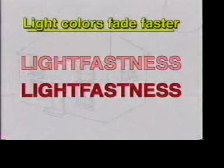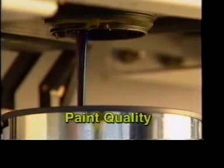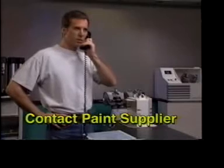This can be caused by differing levels of light fastness of pigments in a blend, or by certain combinations of organic and inorganic colorants. In pigments that are light sensitive, light colors fade faster than dark colors. For instance, a light pink will fade more than a deep red if the red pigment involved is light sensitive. The quality of a base paint being tinted can also affect the light fastness of a color. It's always a good idea to contact your paint supplier with questions about these and other characteristics of the specific colorants in their color system.